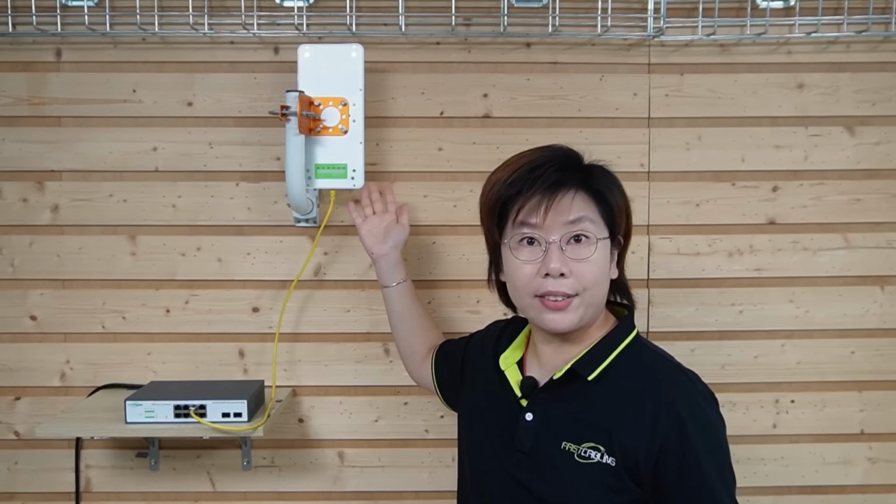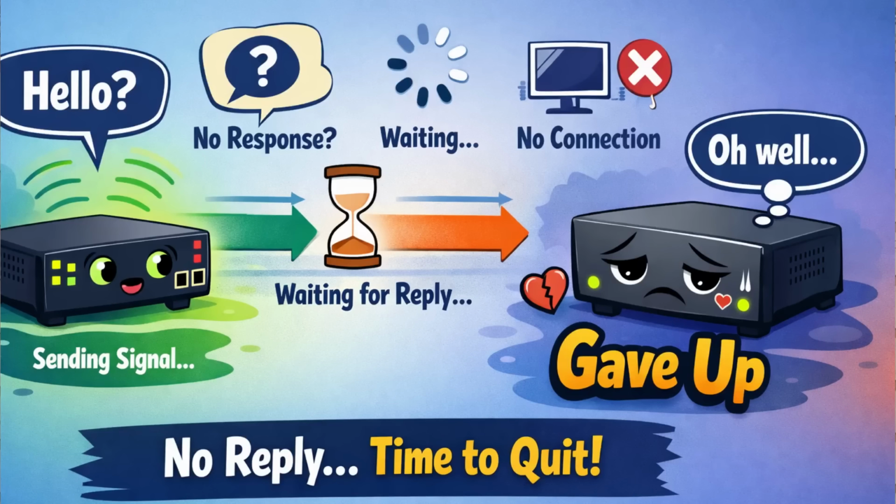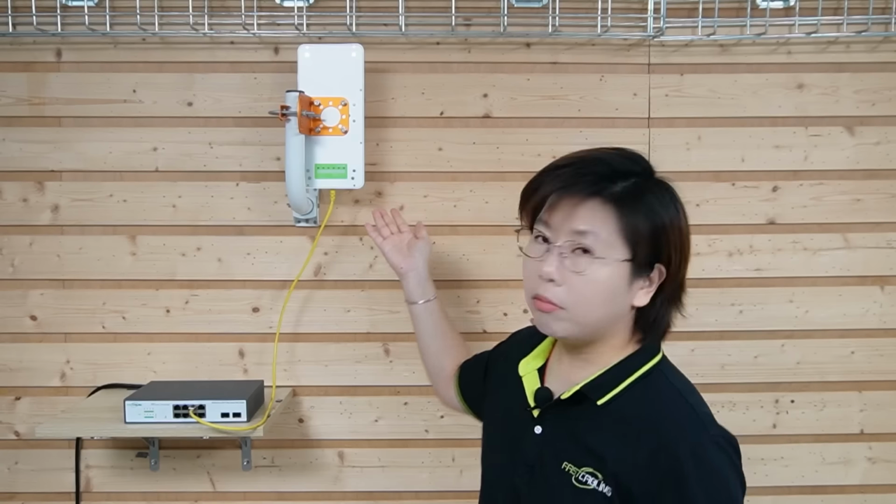But the problem is, our wireless bridge here uses passive PoE. It's the strong silent type. It doesn't know how to handshake. It just expects power the moment the cable is connected. So the active switch sent out its little hello signal, waited for a reply, and when it didn't get one, it simply gave up. It refused to send power to protect itself. So our bridge was left in the cold, literally. So we need a device that doesn't ask questions, it just sends power.